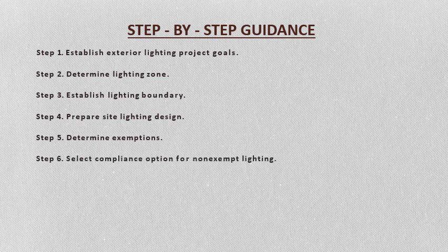Step 6. Select compliance option for non-exempt lighting. Determine which method of compliance documentation the project team will follow for all non-exempt lighting and for each of the two sets of requirements. The two compliance methods are the BUG rating or the calculation method.